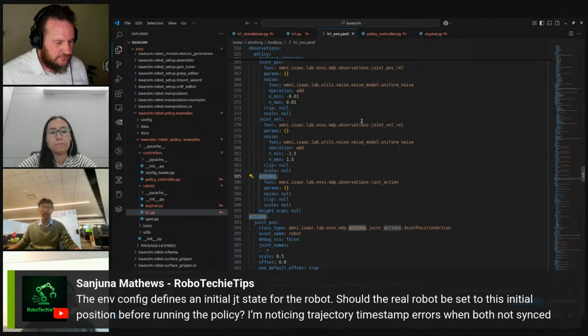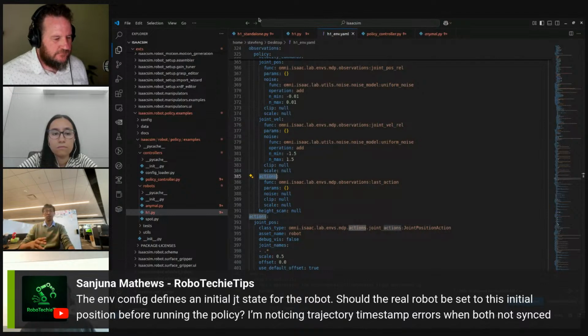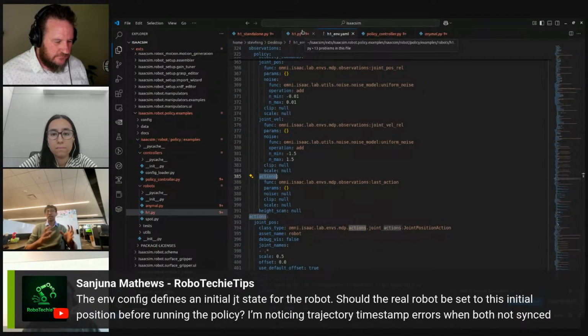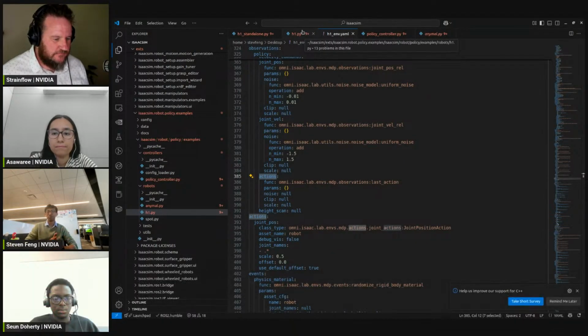Yes. We can show it in a later example as well. But if you were to set the target position in your USD directly and hit play, you'd see that at the very beginning, the robot will try to move towards the target or default position, but it won't actually be at the default position. So in the last part of today's tutorial, we're going to talk about how we can bake those joint states and joint values into the robot so we can start at the default position instead of the 0 position. Okay. That's great.